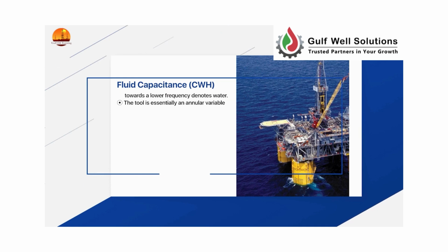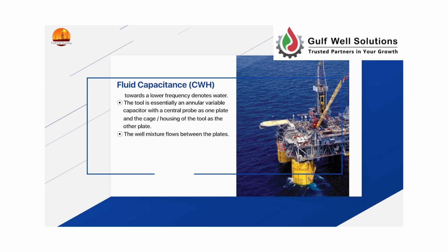The tool is essentially an annular variable capacitor with a central probe as one plate and the cage housing of the tool as the other plate. The well mixture flows between the plates. The average dielectric of the fluid mixture governs the rate of charging of the capacitor.